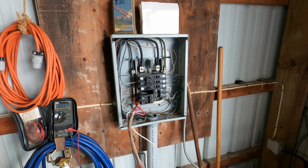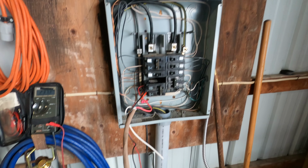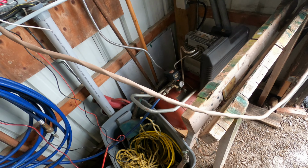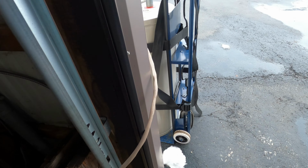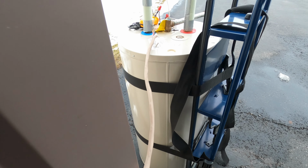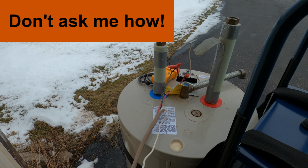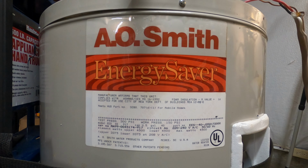Then I'll take the water heater out to my pole barn and connect the water heater load to the barn sub panel. I'll take voltage and current measurements in both places for comparison. By the way, I'll have to put some water in the tank before powering it up. I happen to know that starting a water heater up dry will burn out the heater element within half a minute. Let's get started.